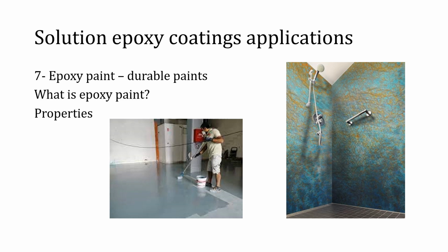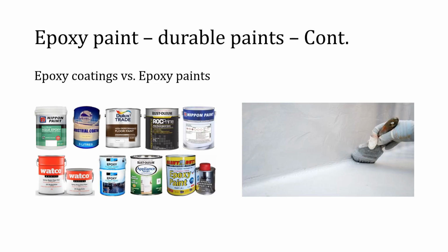The main difference between epoxy paint and normal paint is that when epoxy is present, the paint will adhere to the concrete surfaces much better, making it more durable and resistant. Without epoxy, a standard acrylic paint will eventually peel and flake, especially in high traffic areas. Also, epoxy paint has chemical and corrosion resistance properties. Concerning epoxy coatings, epoxy paint is not as durable as epoxy coating, but it still contains enough epoxy to provide decent protection for many applications.